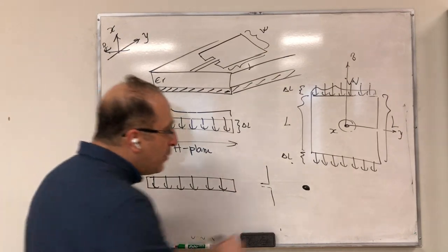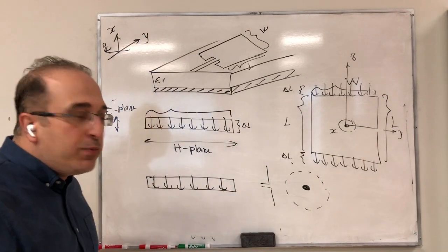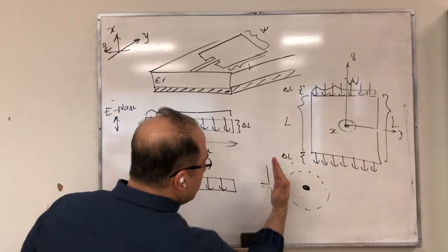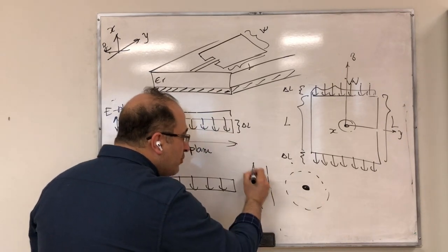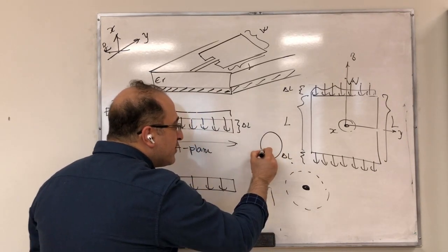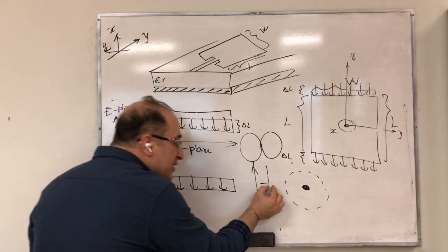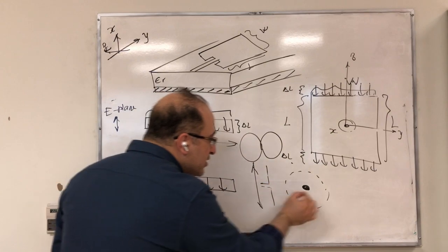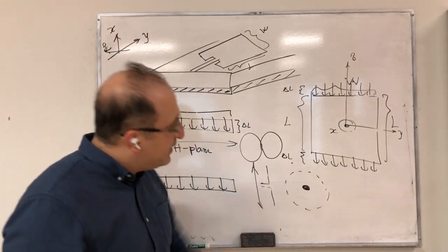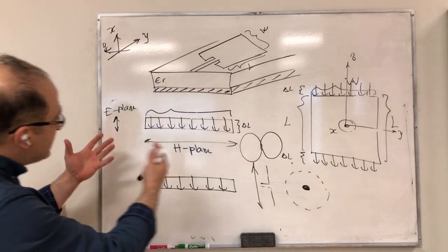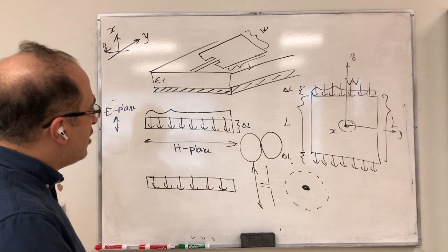So you get an omnidirectional pattern in the H plane. But the E plane, for example, this is your E plane for the dipole, you actually see the whole length of the dipole, and therefore you get a pattern like this. So in the H plane, the size of the dipole is so tiny, it's just a point. Therefore, it becomes omnidirectional in this cut. So this is the discussion on the size of the antenna that you can consider.